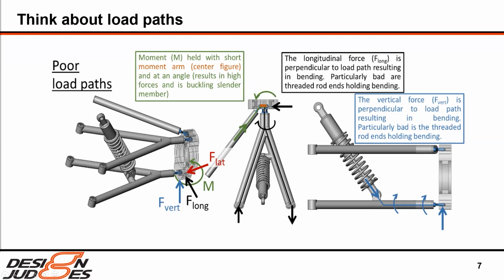And it's going to be offset for two reasons. One, because the center of pressure of your tire might not be in the center of your tire. So you might have some pneumatic scrub and trail, but you also will have mechanical scrub radius and mechanical trail, which puts these forces away from this axis, which will cause moments. So the first moment I want to talk about is this moment on your tire. In the case where you have some scrub radius and you're braking hard, this would be a big moment to consider.